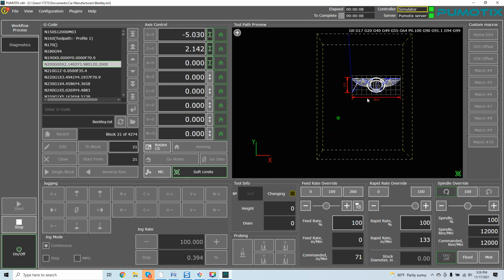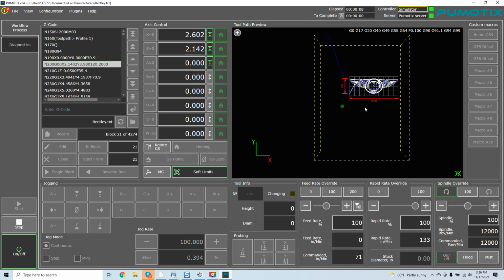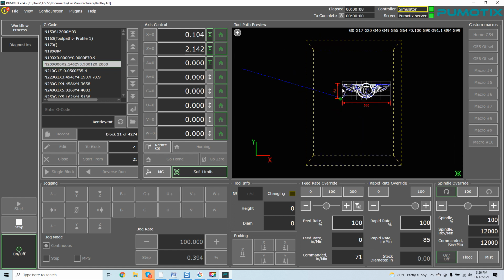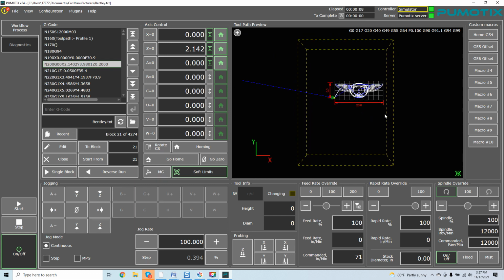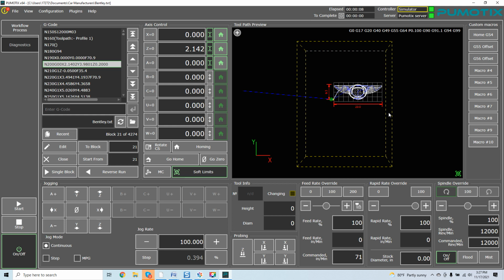And when I say that, guys that have worked with Mach 3 understand just how powerful this is, especially with the fact that you're not doing any measuring other than just putting in your numbers or your table. And again, guys, I always recommend not going to the complete end stop position. Give yourself a half inch if you're using imperial measurement, or, you know, just translate it into metric measurement, at least I would say a quarter inch. I would never go past that towards your end stop. Give yourself some positional room. It's always just best practice. Not that the software won't hit it. It certainly will hit the soft limit setup, but it's always best practice to give yourself a little breathing room.